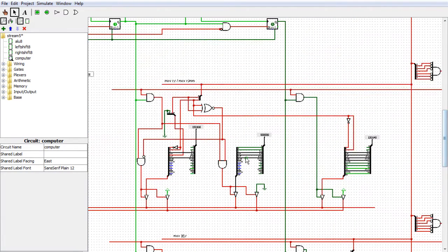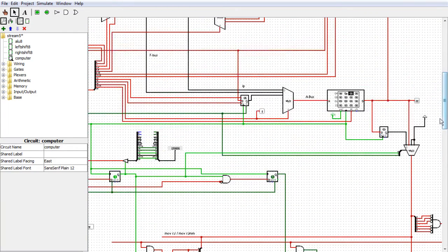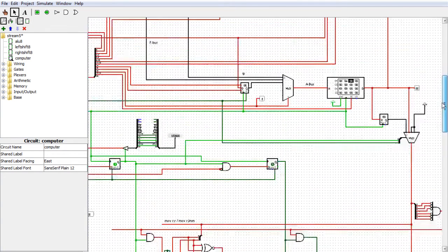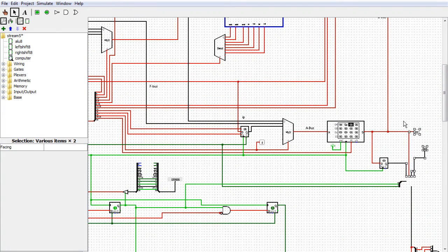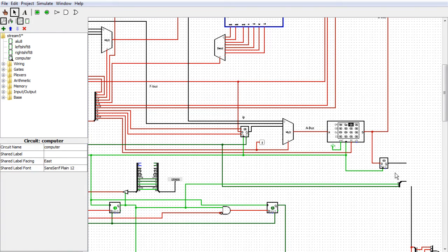It doesn't do anything bad for the immediate move, but it does mess with our register to register move, and it makes it 1 clock slower. And I didn't want to do that. But then I thought about it, and I'm like, well, I don't think I have a choice, because I don't want to deal with this feedback loop nonsense. I know it's going to come up again. Even if I find a way to fix this problem, there's going to be another problem when I add a new instruction. So in the end, I said, you know what? Forget it, it's not worth it. Life ain't worth it, and I got rid of the multiplexer thing there. So say goodbye to that because it's never coming back.